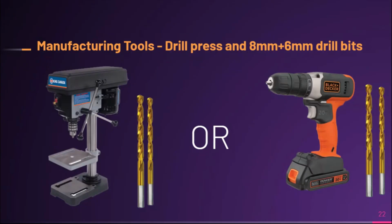The next thing you'll want is what I talked about a little bit earlier, a drill press. A drill press typically has a 3-jaw chuck where you're able to put drill bits, and then when that chuck spins and the head is lowered onto your material, a hole will be drilled into the material. The advantage of a drill press is that it's very stable and always makes perpendicular cuts.